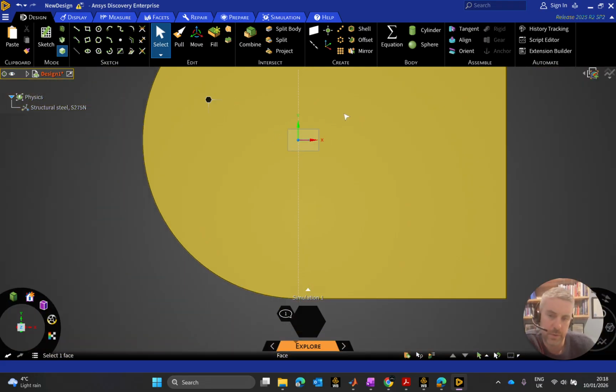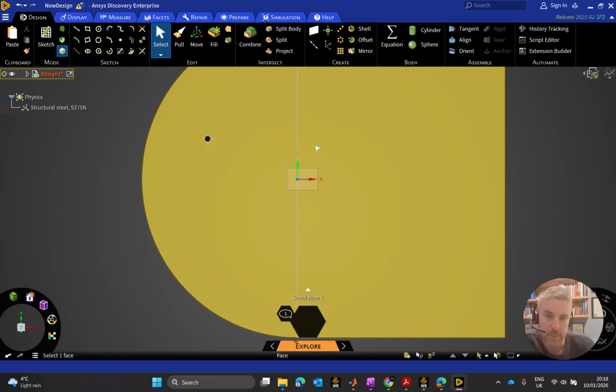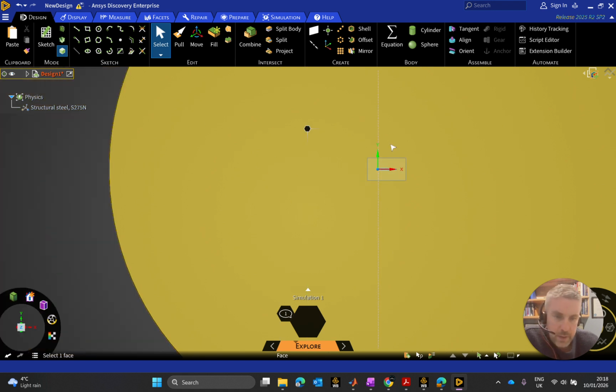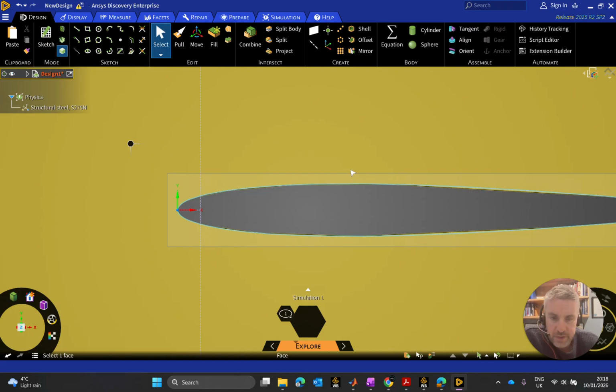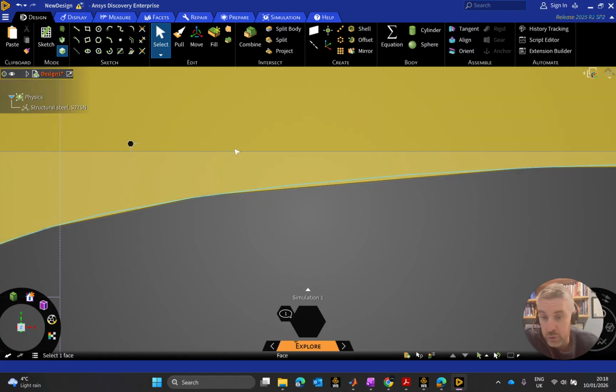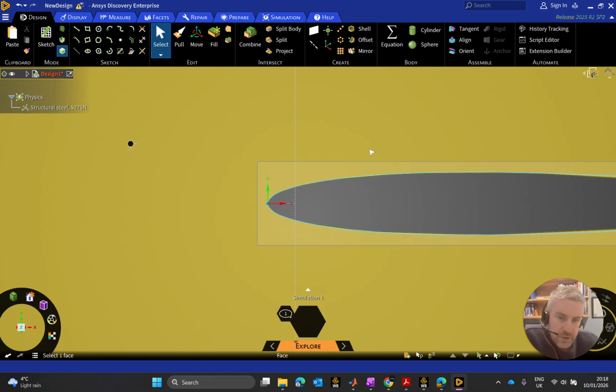What I want to do now is split this domain up. There are a couple of different things you can do in meshing. I should actually do a copy of this and show you the difference between a structured and an unstructured mesh. But what I can effectively do is not do anything. I can just bring this into meshing. I can discretize or split this whole yellow flow domain into a series of cells, just a big grid, and then provide an inflation layer, which is a very refined and thin section of ever increasing cell heights from an initial cell height, which is going to be based on what's called the Y plus value. We'll deal with that in a later video.